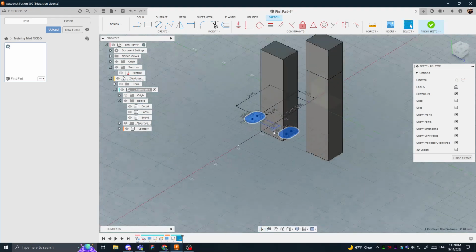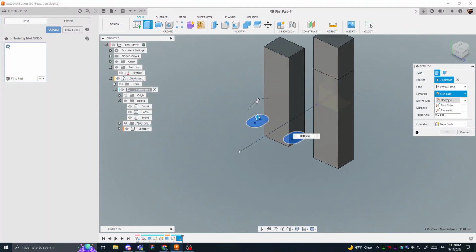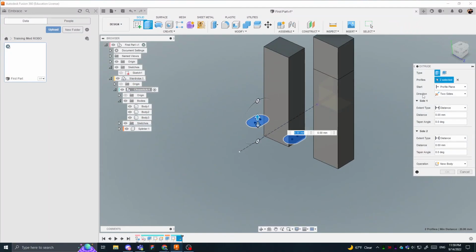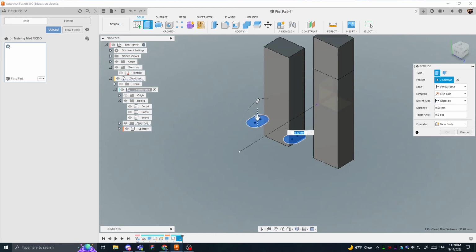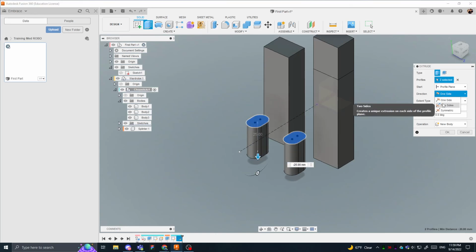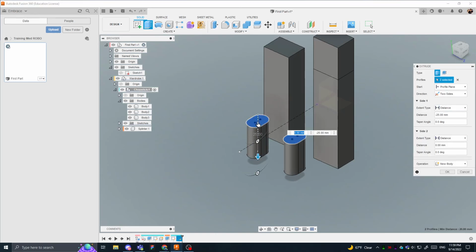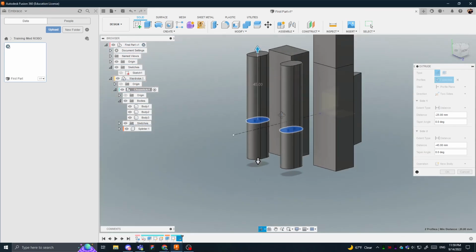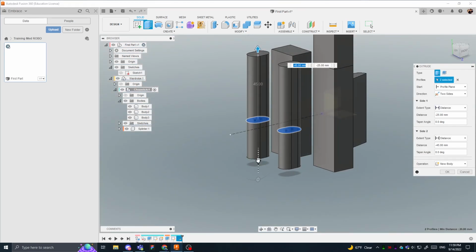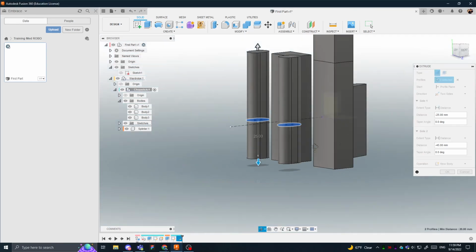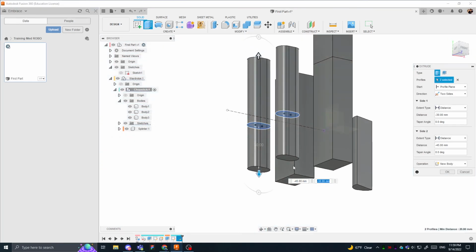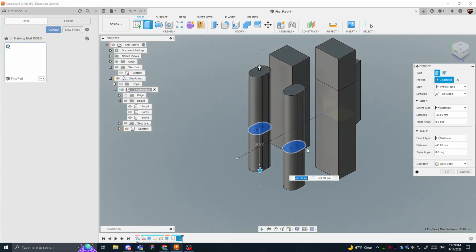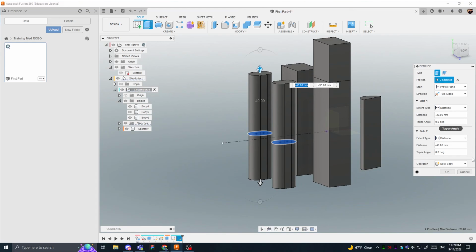I'll just pull them into 3-dimensional space. I can also say 2 sides extrusion. The directions, I can pull it in one direction, like up or down, or I can say I want 2 sliders, so I can pull one down and one up, so I can make it asymmetric, or I can pull them in different directions, certain lines. When I click on this arrow, I'm directly editing here, so I can just click on this to say go to that height, so these should be equal. And if I click on here, I can say go to that height, so that should be equal.